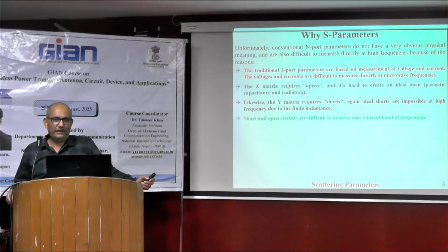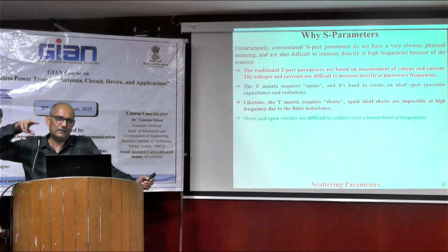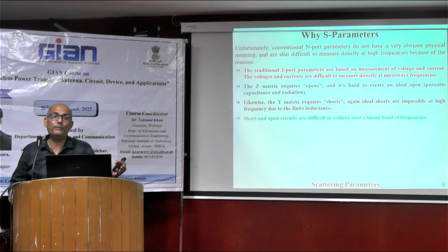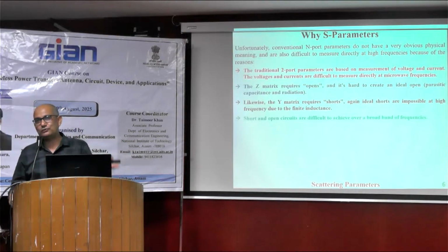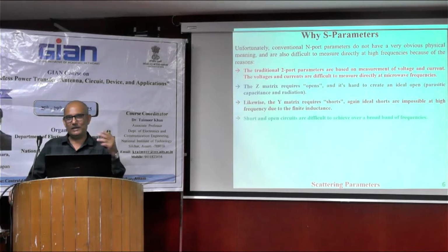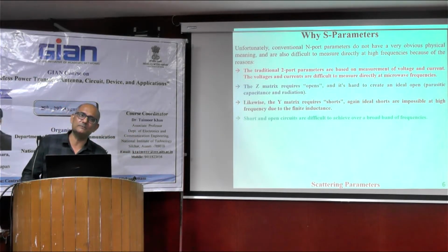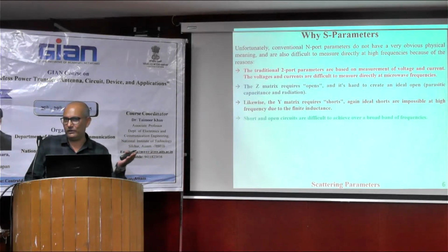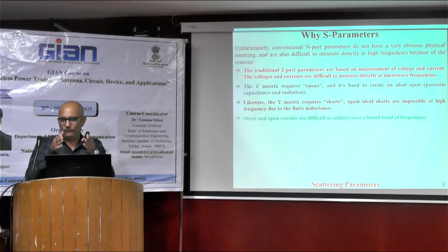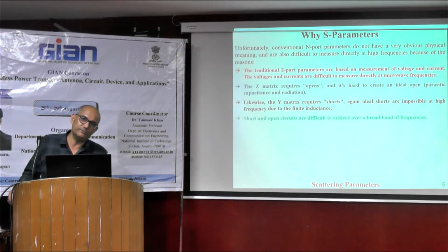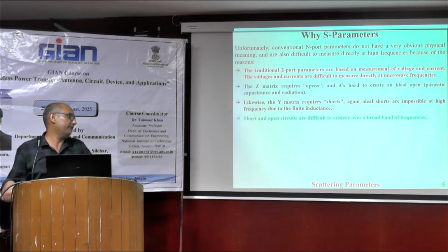In traditional power systems, in core electrical engineering, the reverse phenomenon is there: people who belong to core electrical engineering used to play with variations in the voltage at a constant 50 Hz frequency. But here in communication and high frequency systems, we need to have a constant voltage, but the frequency will vary over a wider range. Then creating open circuit and short circuit conditions for wideband, ultra wideband, super wideband is quite impossible in a high frequency system.